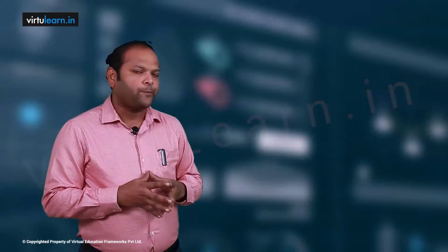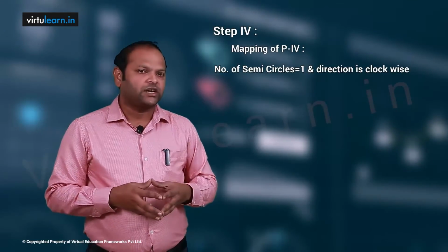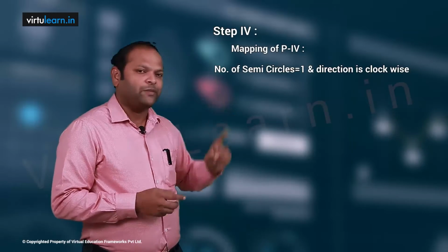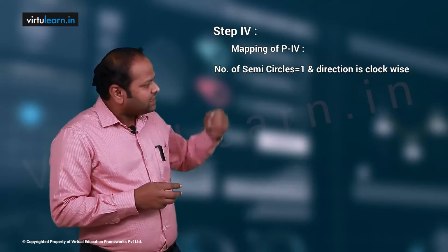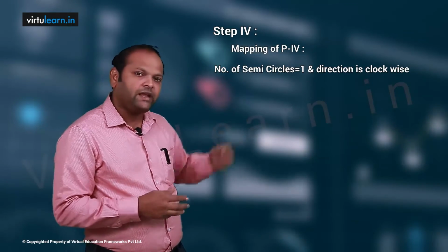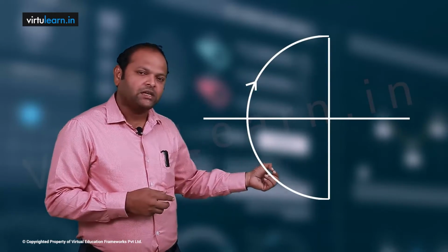Now how to map path 4? When you map path 4, look at how many poles are at the origin. There is only one pole at the origin, so we will get only one semicircle. And what is the starting point of path 4? The starting point is the ending point of your inverse polar plot. The inverse polar plot ending point is here at minus 90 degrees.